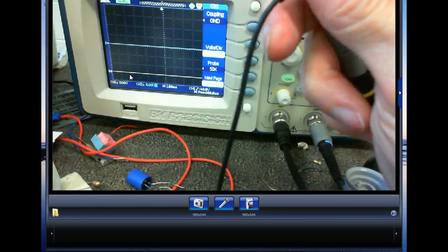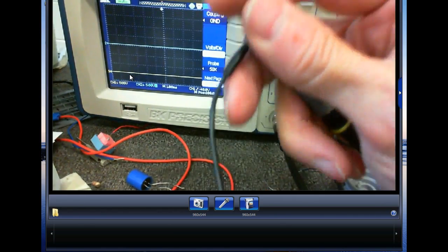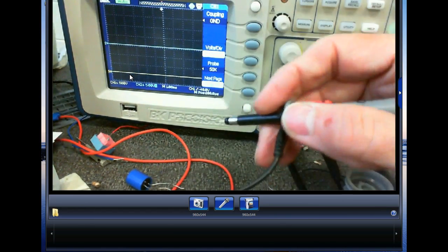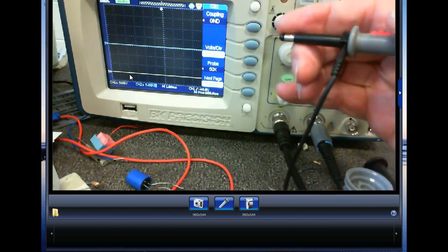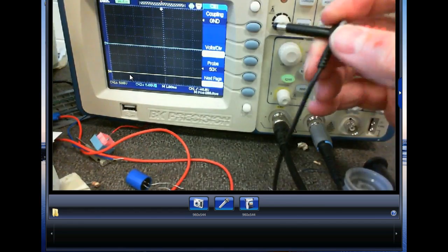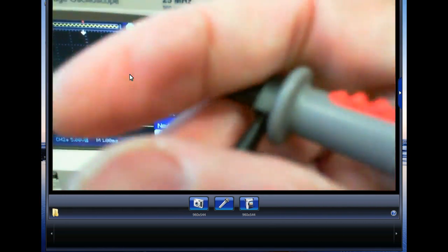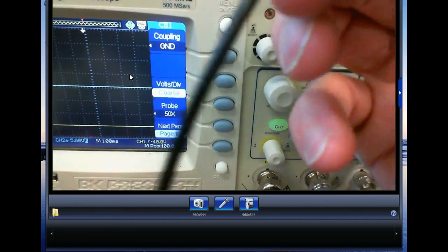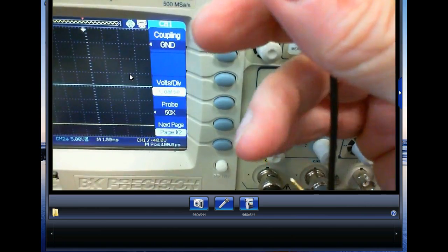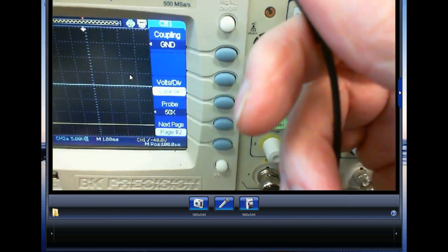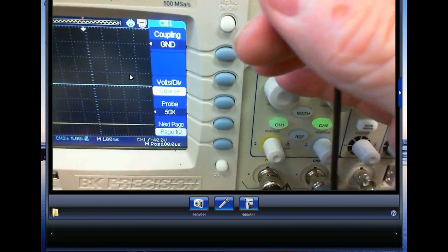So I've seen people blow these guys up by taking that cap off and probing inside a circuit and letting that sucker right there touch up against something. So you've got to be real careful. That's a big magnet there. I've seen these little leads right here just vaporize, where people hook it inside a high power circuit, and it just vaporizes right in their hand.